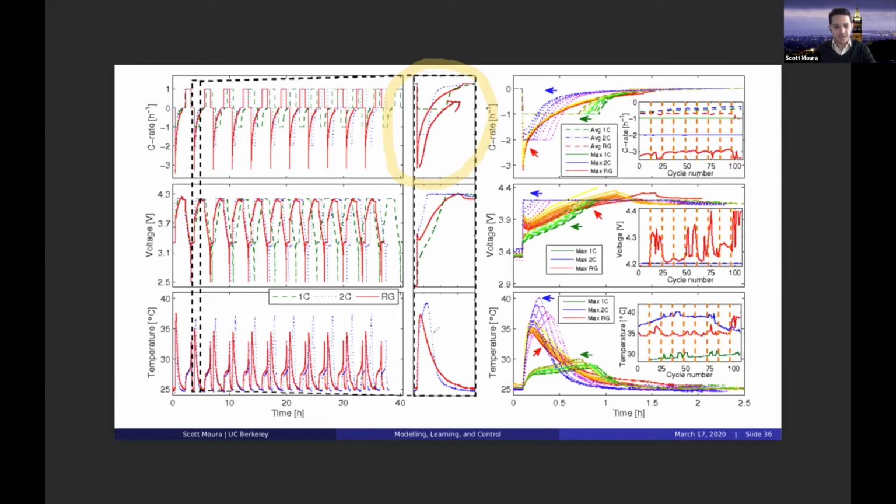Now, interestingly, when you do that, the temperature is not building up. And in fact, you can see that the temperature overall is not building up much in many of these methods. And it suggests to me actually that SEI growth may not be dominant here. It's really lithium plating that we're worried about. That's in contrast to, say, that recent paper by Will Chu, where we have LFP.